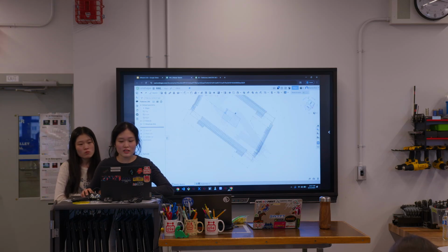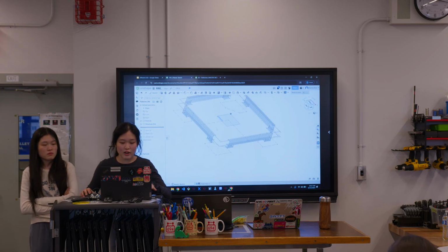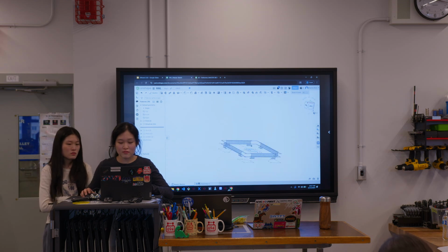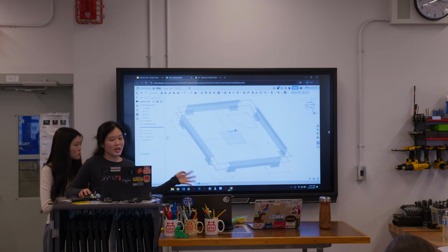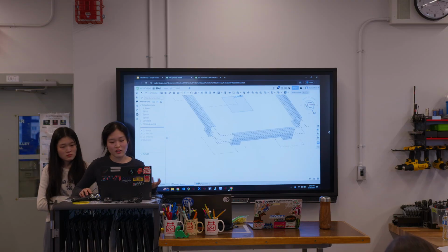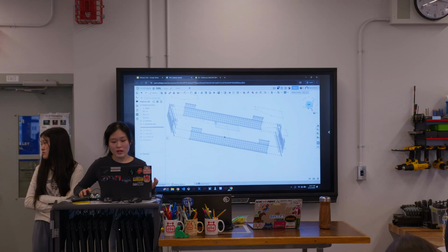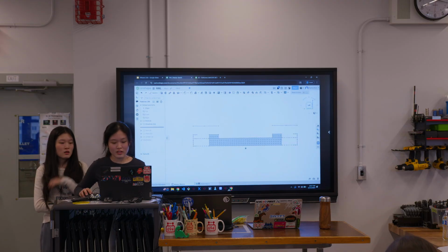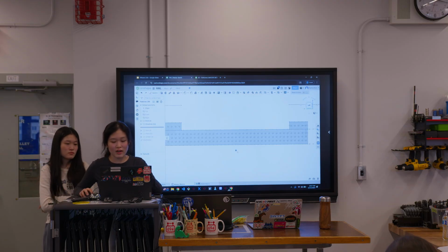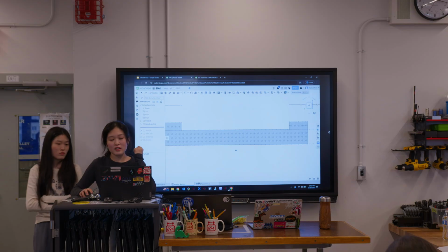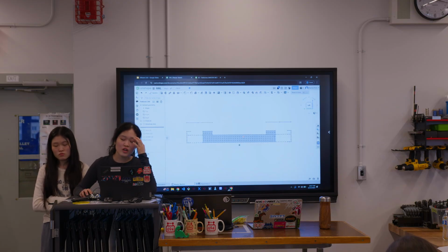So for instance, this is only the drivetrain part of it. If you see here, it's very three-dimensional, like I mentioned before. You can make out the shape and size of the tubing based purely on sketches from this bottom view. It's going to be mentioned in the slide later, but if you see here, the drivetrain tubing is not directly at the origin, and it's floating above. This is because obviously you have the swerve modules, so your tubing won't be directly on the origin.